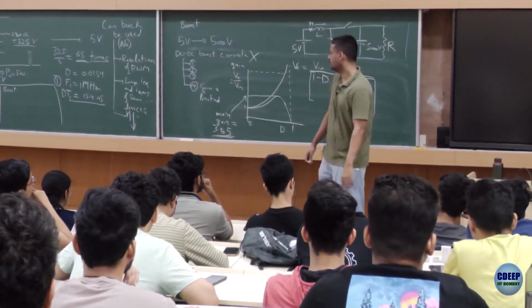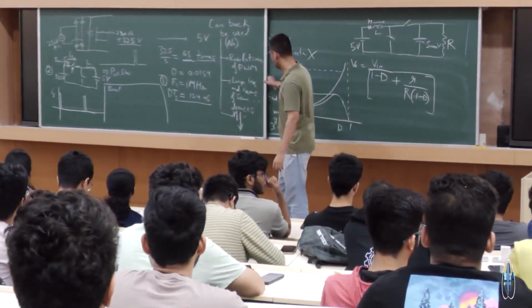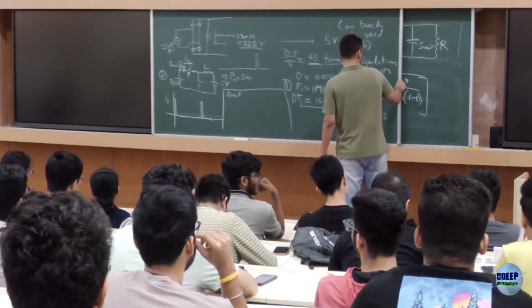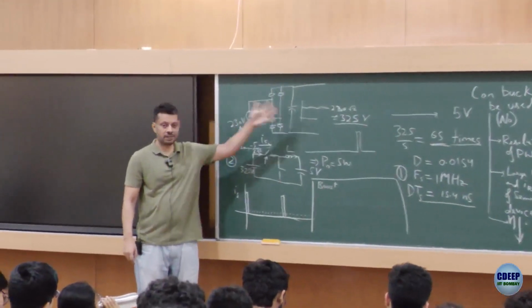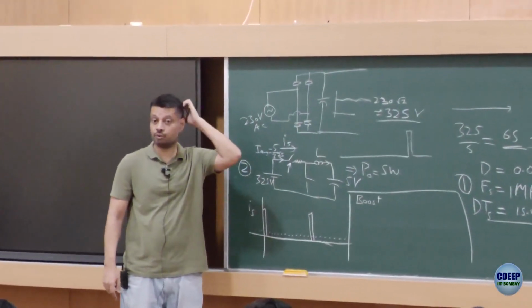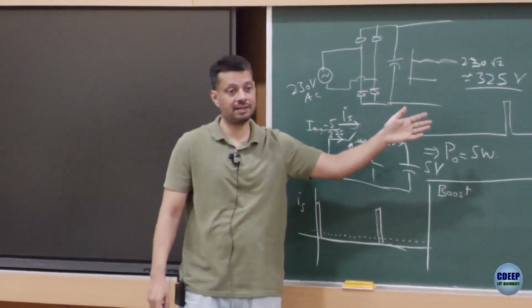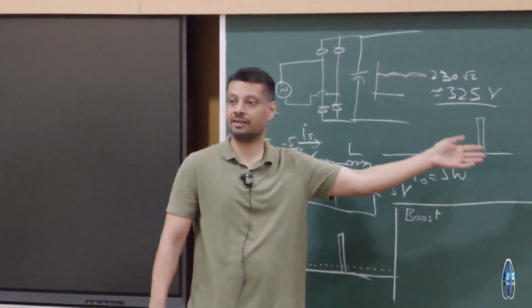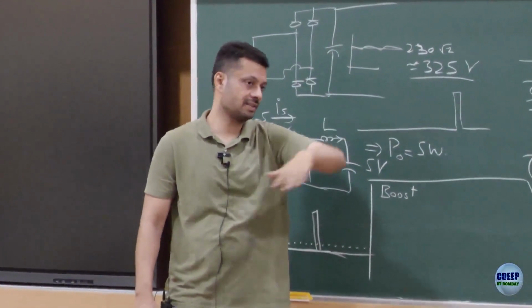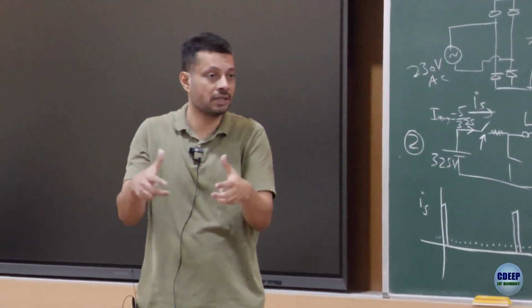What he's saying is that once you rectify, let me bring back this board. Once you rectify, you can place an inverter again, and now you create a very high frequency voltage, then you put a transformer, which will step it down, then you put a rectifier again, and then you would get a low voltage. Yes, that's a way. And we officially have names for these sorts of converter topologies.